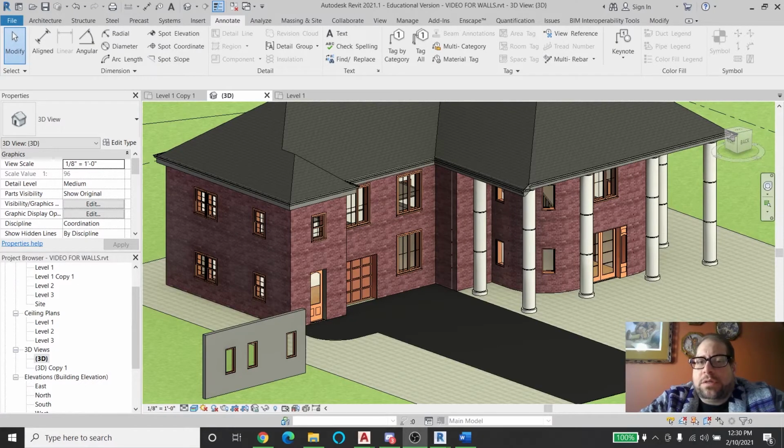Revit. Dimension driving is using temporary dimensions in order to move items around that have already been placed, so they end up being in the exact position that you prefer, and more importantly, relative measurements all around them are what they expect it to be based on plans or based on future planning. So let's take a look.